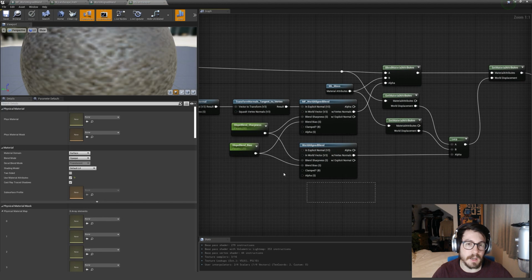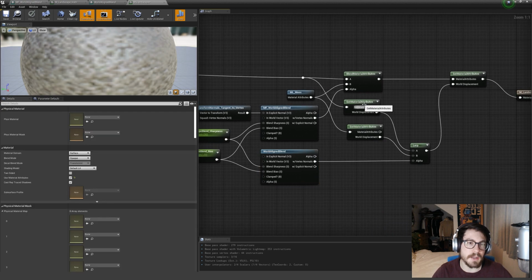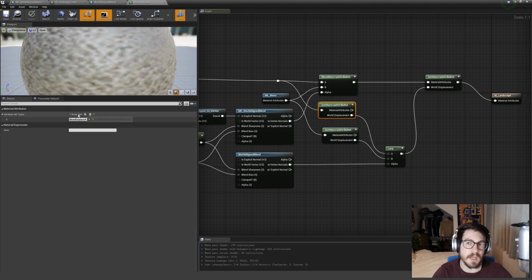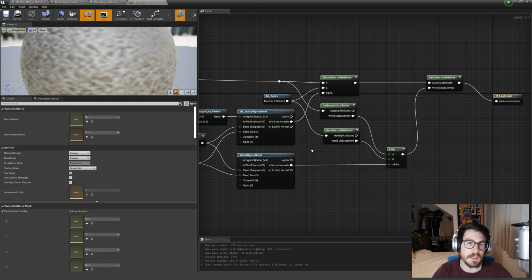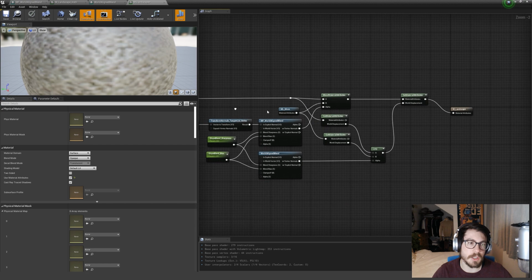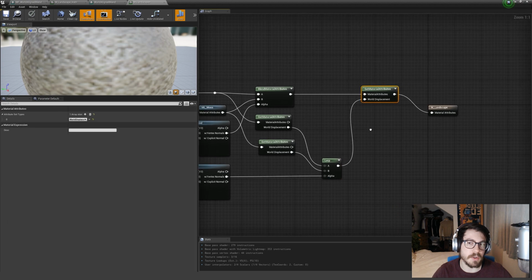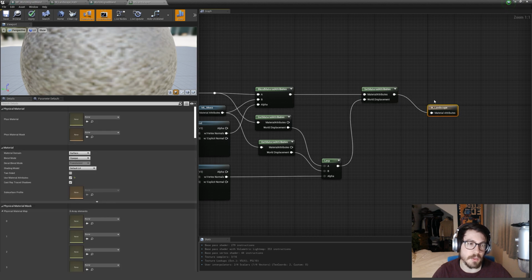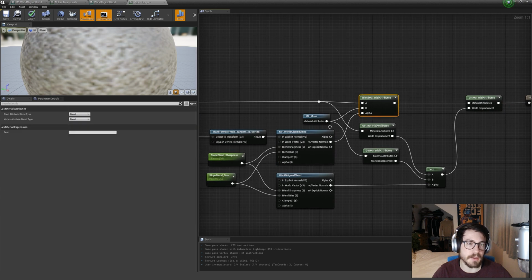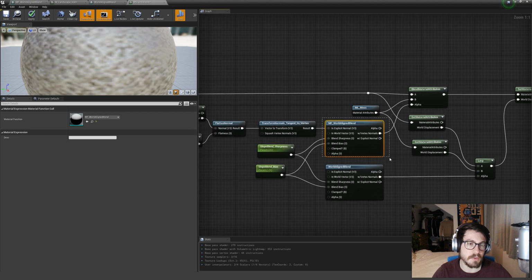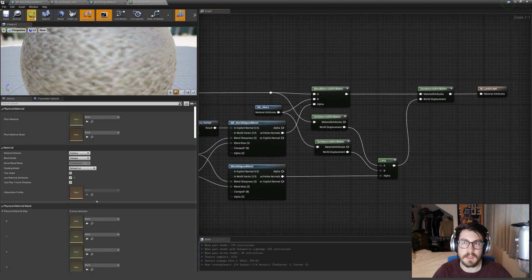Then I'm basically just connecting all of this again and using that to blend just the get material attribute world displacement of each one, so the moss and the rock. And then I'm just lerping between these two displacement material attributes, and I'm setting this material attribute here again, just the displacement attribute, and the rest of the attributes will take the ones that we have blended here with this function. And that should work pretty fine now.